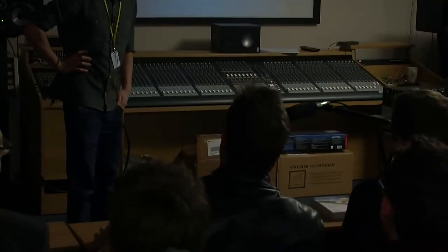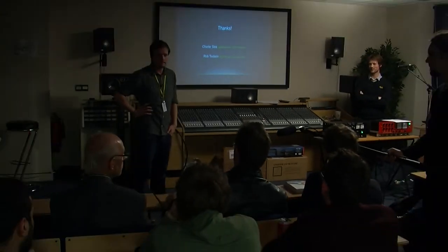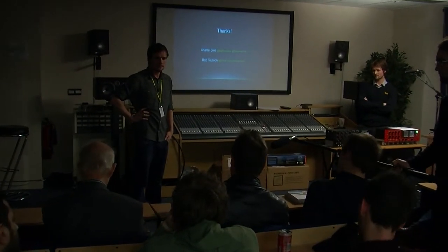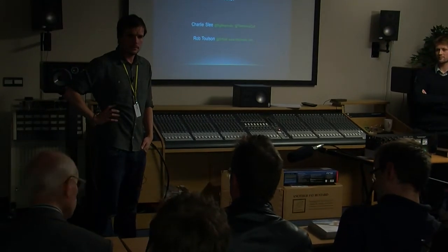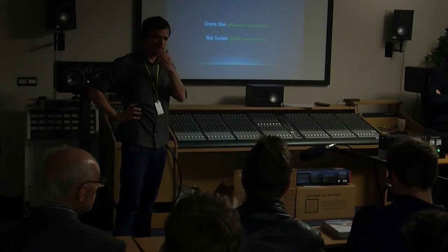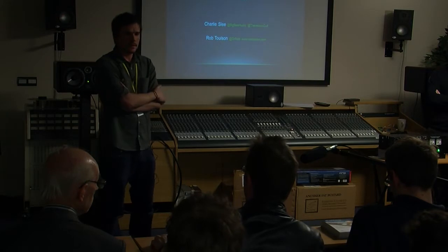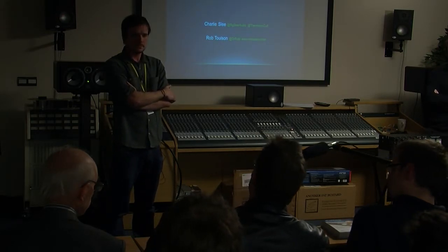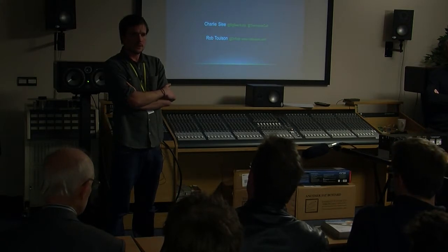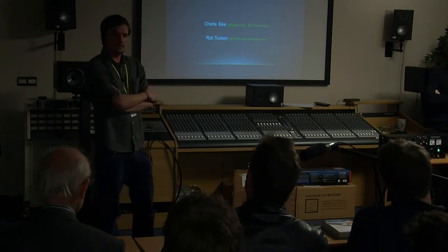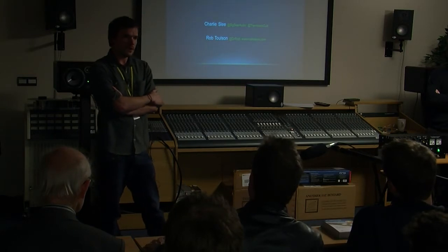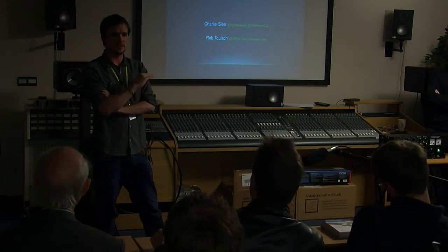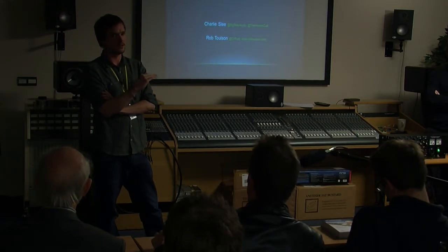Hi. You mentioned second harmonic distortion, the classic low-order distortion that gives you the valve sound. You also showed the Altec schematic with differential stages, and you indicated you've got adjustments in your products to balance out distortions. Does that not reduce the second harmonic, especially if you start balancing the stages, and therefore emphasise the higher harmonics? Yeah, it does. Well, I think the higher harmonics are almost unmeasurable, really. So it's not an issue for us. It's still dominated by the second.